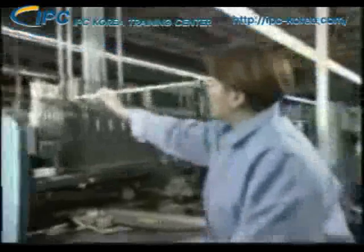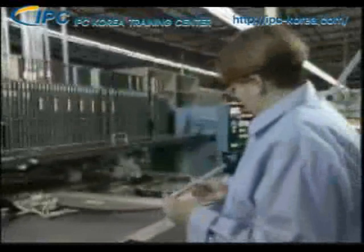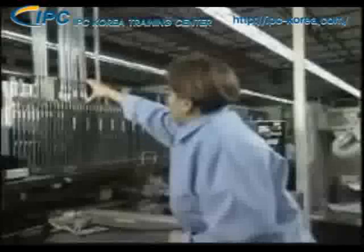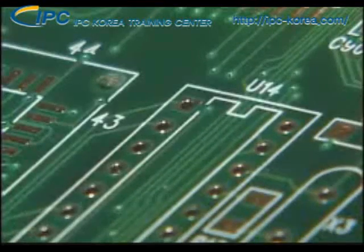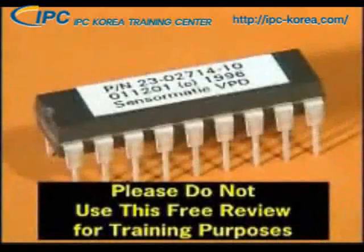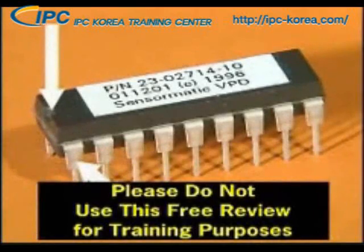The DIP consists of 2 rows of leads and the body is made of plastic or ceramic. DIPs usually come from the manufacturer in tubes. The tubes protect the components from ESD and lead damage and are designed to load the components into the feeders of automatic insertion machines for component placement. The most common reference designator for an IC such as a DIP is the letter U.